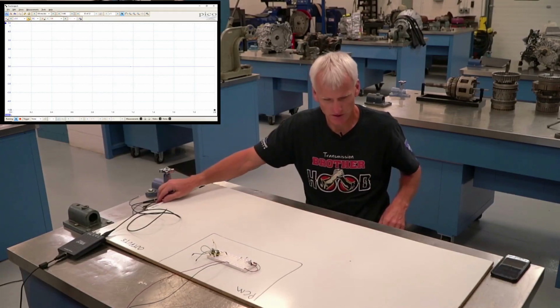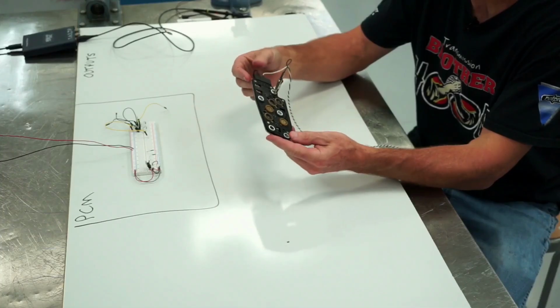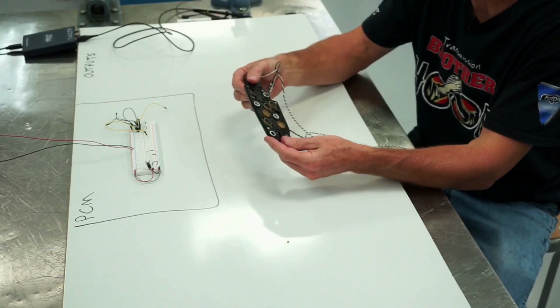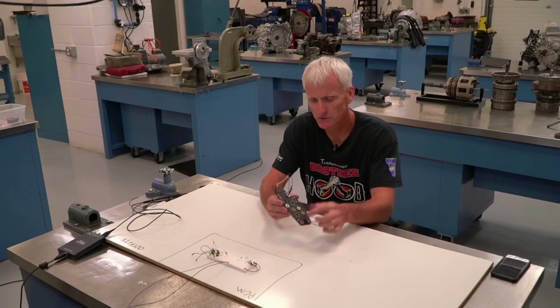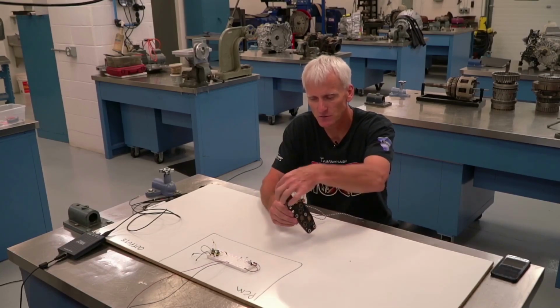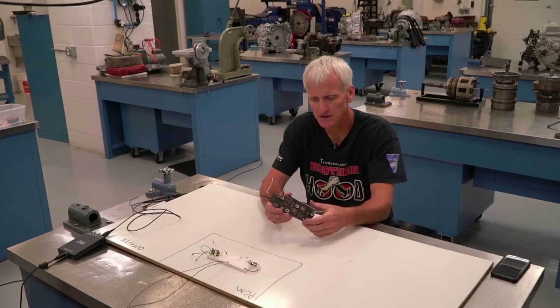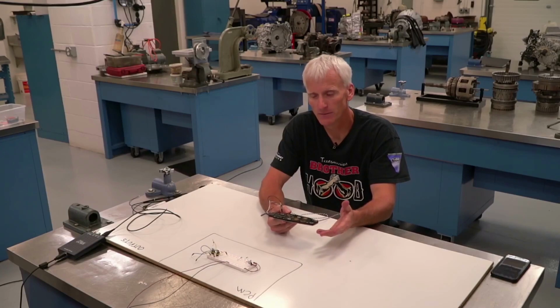All right, so first we're going to start out. One of the first things we talked about was a range sensor, and it's an earlier model. They actually got rid of these on the later model 4L60s. This is pretty common. It's probably off the most common transmission in the world, but there's a couple things in this range switch. We've got 3 channels, A, B, and C, and then on this side where you can see these wires that are twisted, that is a temp sensor, so we'll look at that afterward. But this is going to be an input.